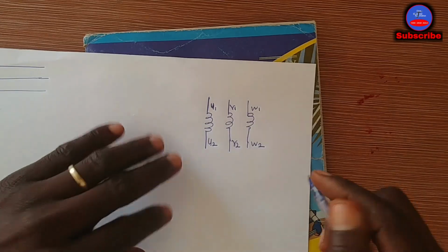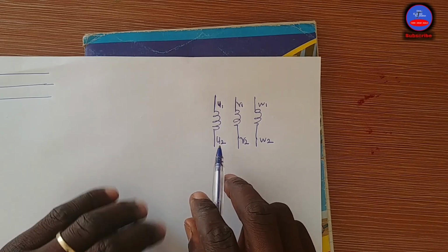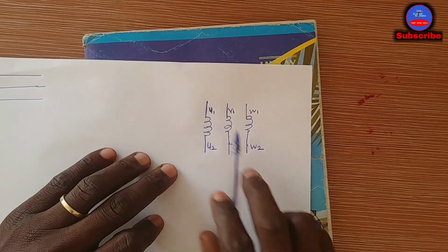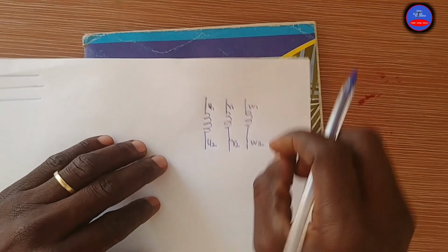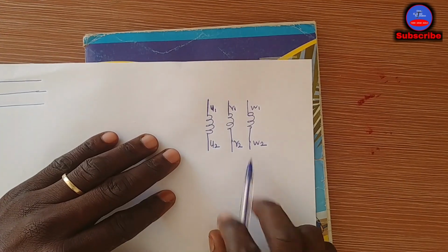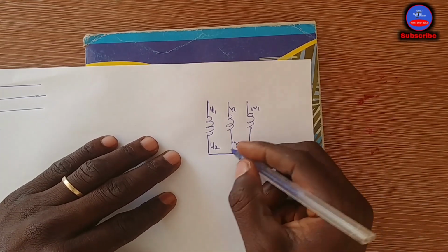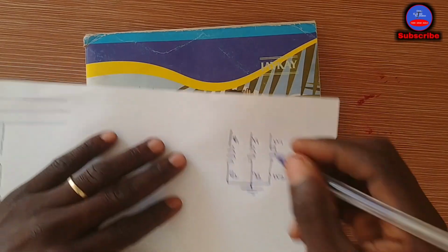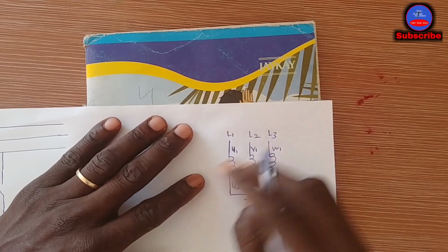So what you're going to do is connect the motor terminal block in star. We would join any side, either here or here. You can join the U1, V1, W1 together and put the power on the other side, or you can join those together and put the power here. So we are going to join the U2, V2, W2 side. When you join it, it becomes a star point or neutral point. Then you put the power here, line 1, line 2, line 3.